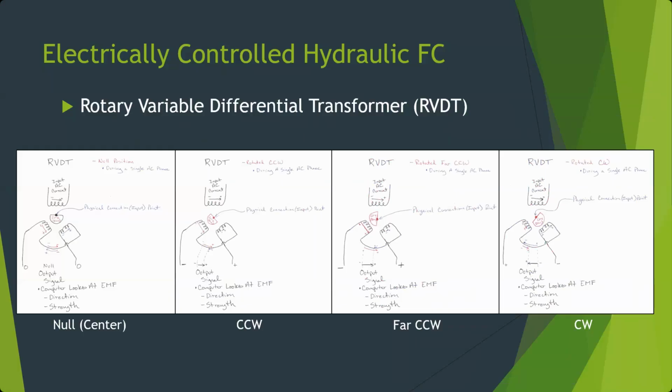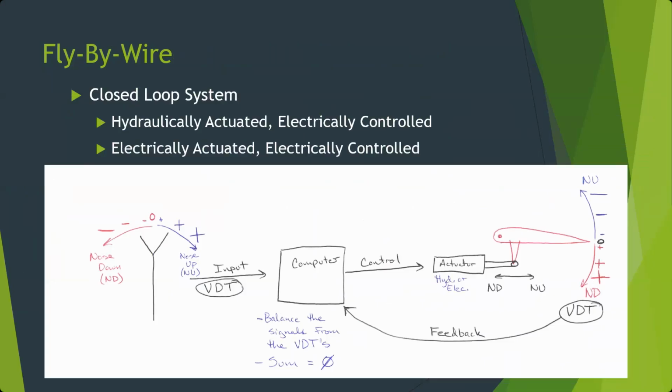On flight controls, we'll get to what are called flight control laws in a second. If you lose certain amounts of signal or other things like that, there are reversionary modes to make sure that your flight controls still work properly. So here is that loop of control, now with a fly-by-wire system rather than the mechanical system.